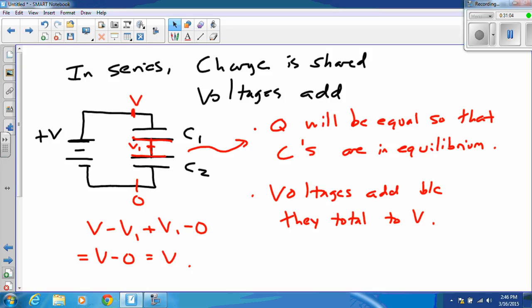If I look at the other connections, this guy is connected here and then out to what we call the positive power bus, this red strip right here. This point is connected to everything in the same column. So when I run this jumper wire from here to here, I'm connecting this to that, which in turn is connected back to the positive end of my power supply. This blue column is called the negative power bus. And when I hook up the negative power bus to the negative part of the power supply and connect that to the rest of the circuit, that's connected also.